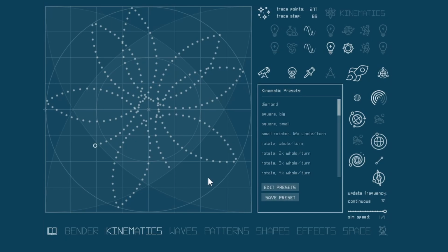This function has some limitations. It is using brute force to predict the end result, so it basically plays every step as fast as possible, placing trace points along the way. In effect, it creates high CPU load. As you can see, each trace takes several thousand steps to complete, and the number will grow if you add trace points or increase traced step.